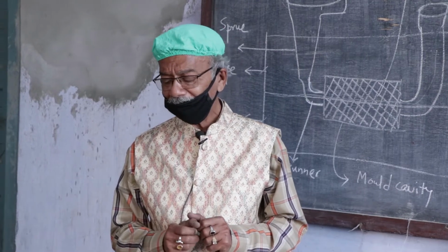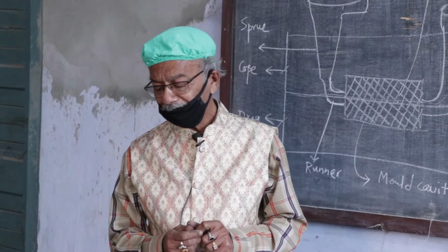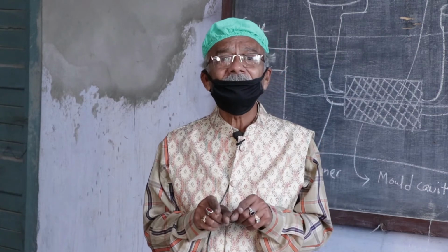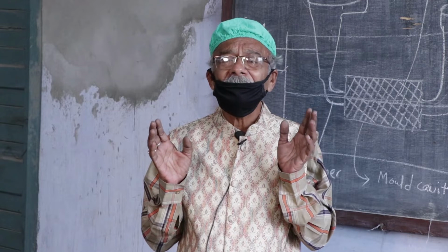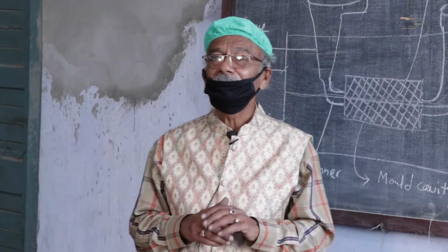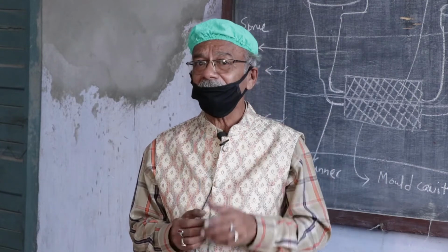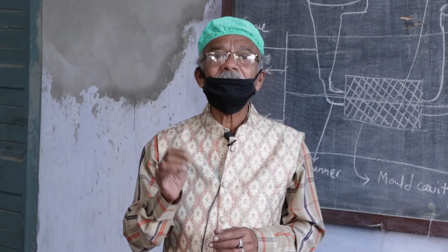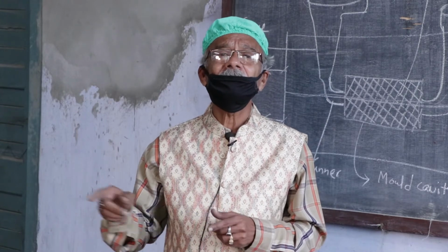After this, another authentic test is dye penetrant inspection. If there is any crack which we cannot see with our naked eyes, with the help of the fluorescent dye we can check whether there is any crack just below the surface or not. Another crude technique is the application of sound. If it is possible, hold or hang the casting and strike it with a mallet. Mallet means a hammer made of wood.